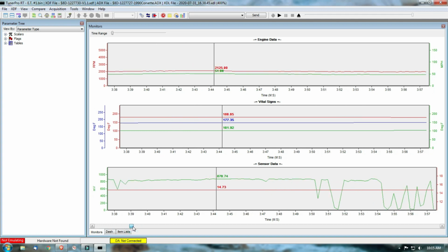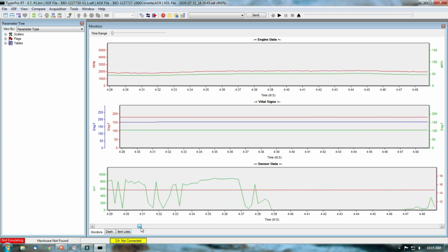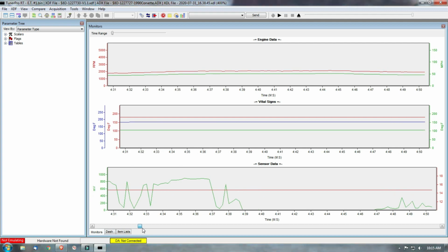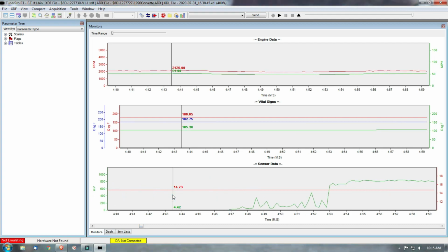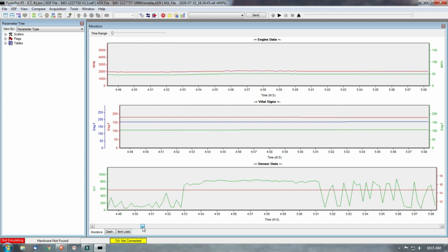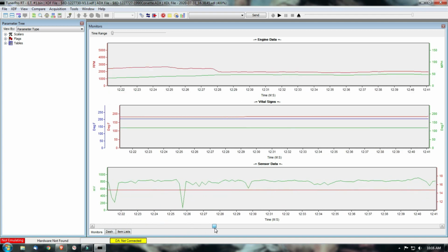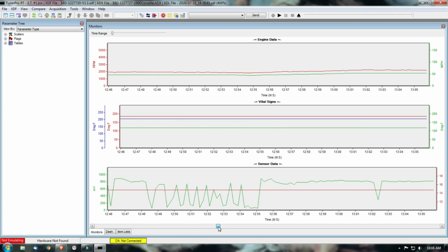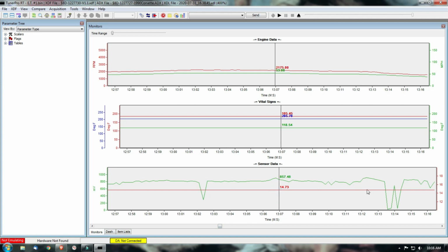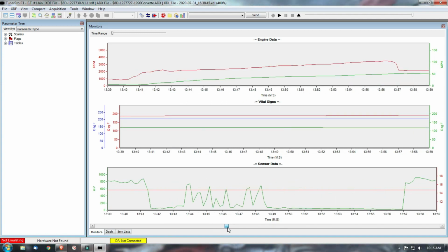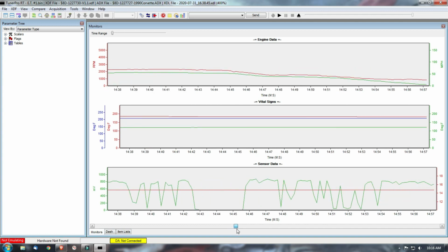It should be up and down in a certain range, and that's not happening. It's running rich there, and here it's lean, but I could be deaccelerating right there. But it doesn't matter. On the wideband, it was showing lean while cruising down the highway at around 70, and here it's running rich at lower speeds, like around 50, and it just isn't right.